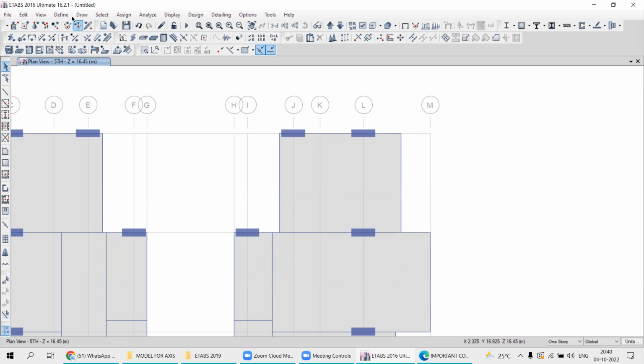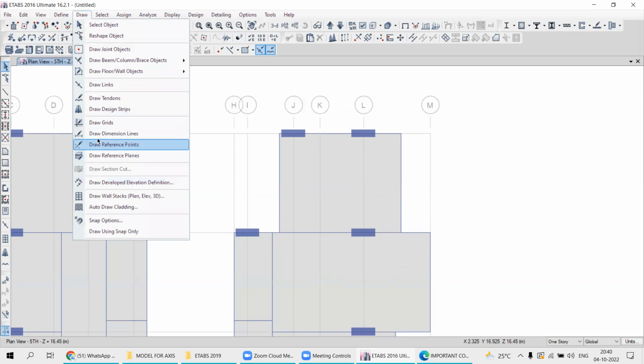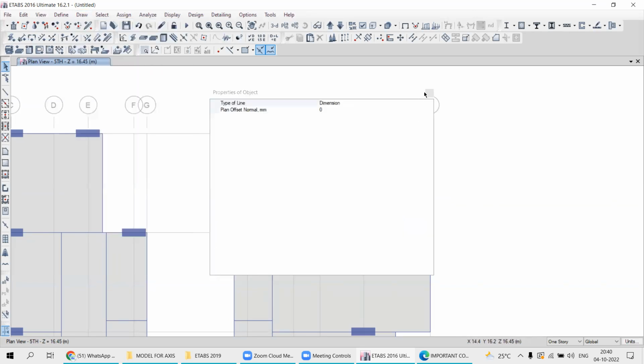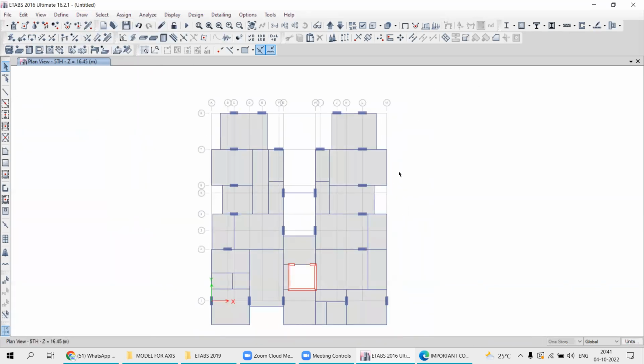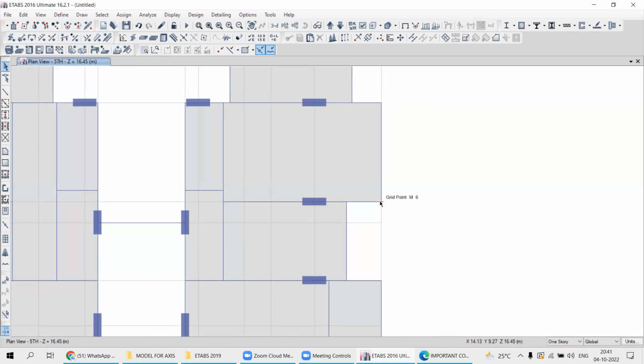Okay, so how can you do that? Go to draw dimension line. Now close it. If you want to see, just to check, click on this first point, freely move to this point. Don't click over the other point, otherwise it will be permanently drawn or fixed here. If I click here, take it outside, and then click here, it is permanently giving the dimension or distance as 2.9.